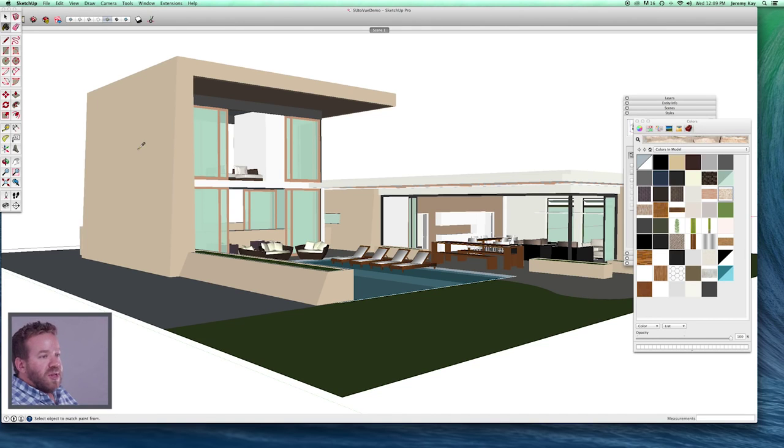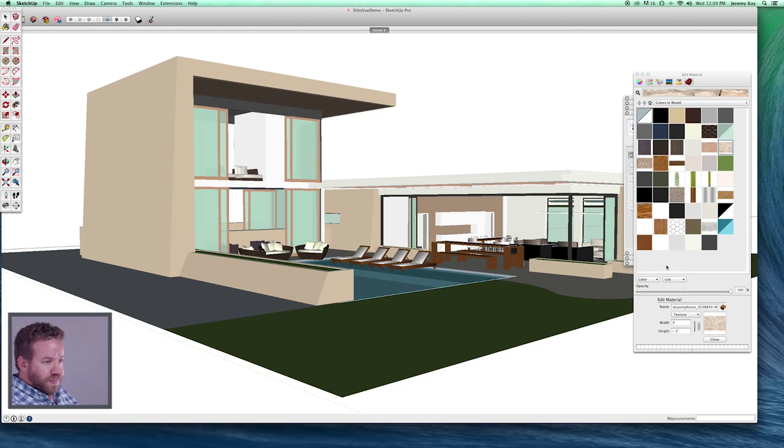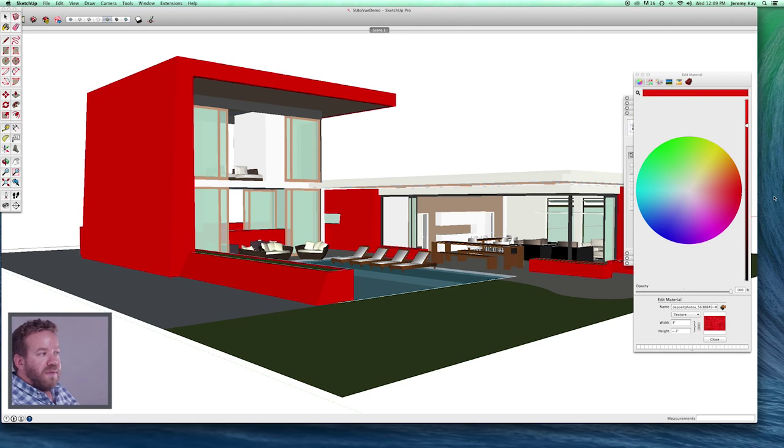What I'm going to do is select the stone material here, and double click that to bring up the options to change that material, come up to the color wheel, and let's just have fun. Let's just drag that all the way over to red. So now in the shaded texture, all my color is now a bright red, which I know is going to be very easy for me to select in Photoshop. The brighter and more saturated, the better. So I'm just going to brighten that up here and close.